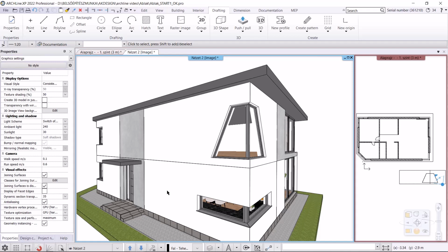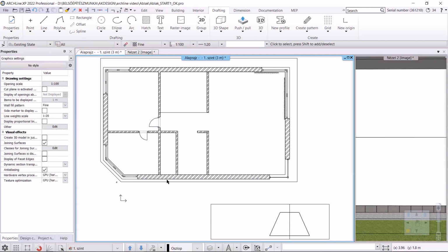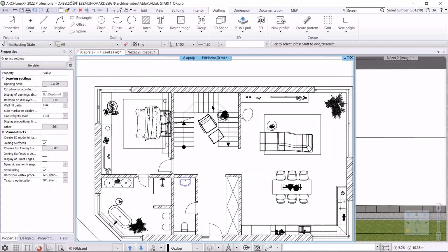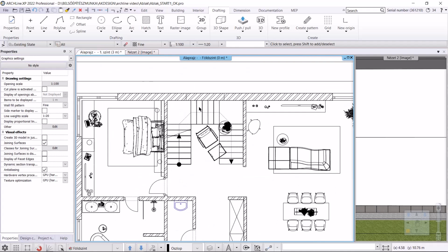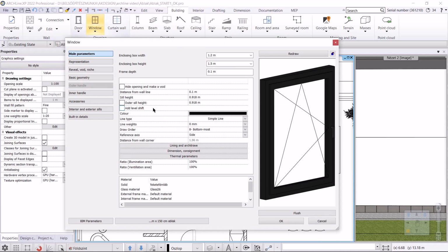The last topic is the creation of the staircase window, which will cross 2 stories. For this I will switch to the following view A06. This is where I will make the staircase window. To do this, I'm going to activate our floor plan view again, and work in that. I will activate the ground floor, because that is where I will place it first. To do this, I have previously drawn the polyline, and then I will specify the properties of the window.